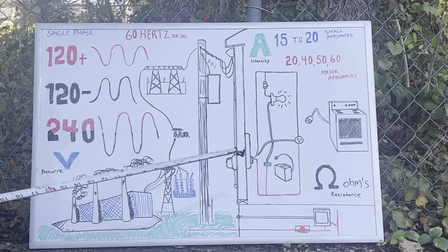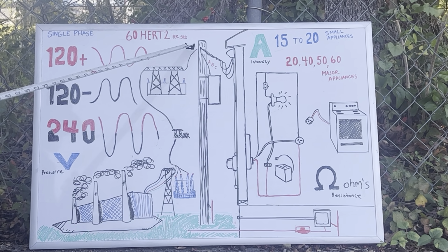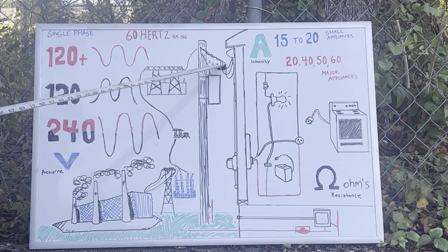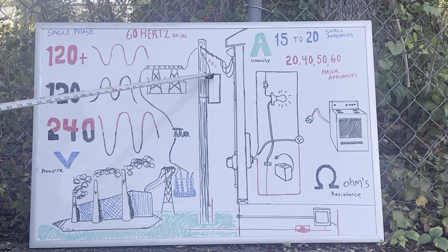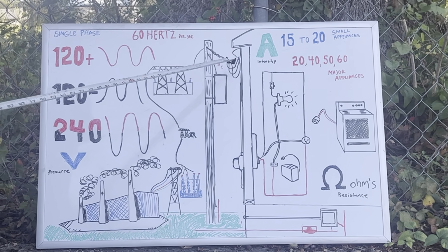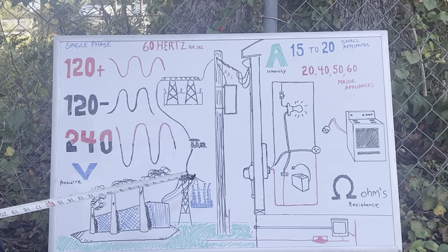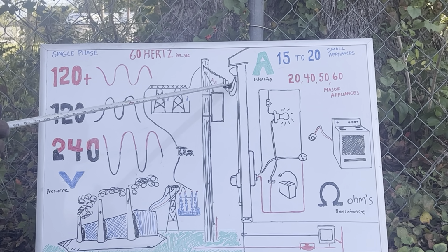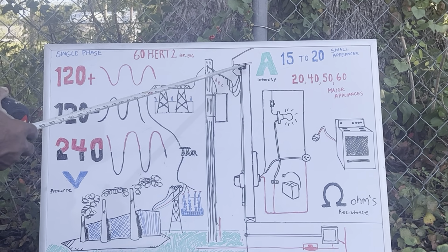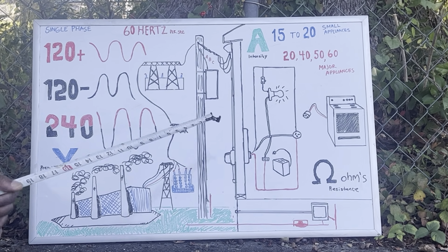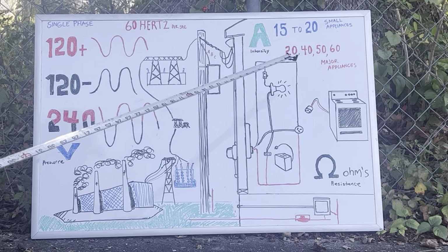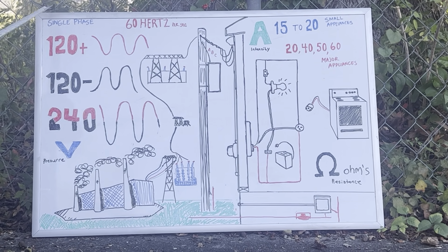So usually you're dealing with 3 voltages. You see this? I've got A, B, and C. This is called your service drop, because it's coming from your utility pole and it's going to distribute into your residence, right? You've got your service drop with an ABC wire, and you've got your weather head right here that's protecting your cables, okay? So once it goes into your home, you're dealing with single phase.